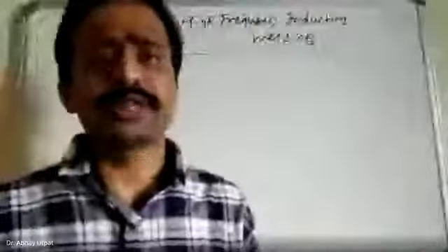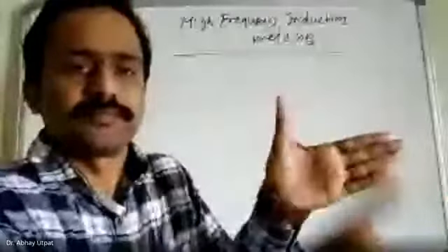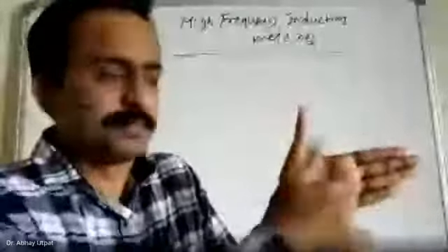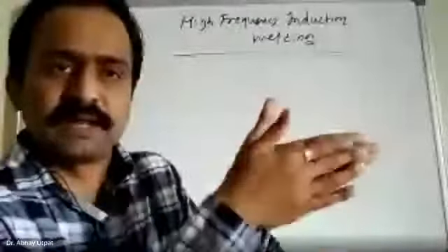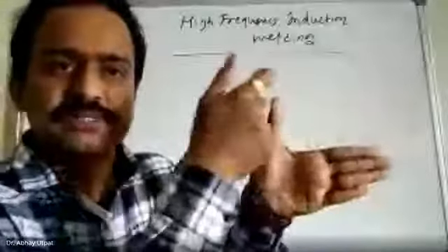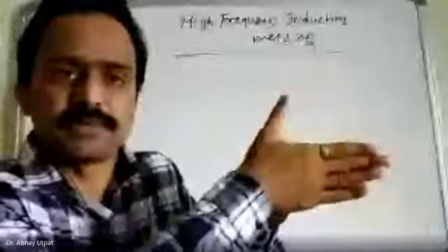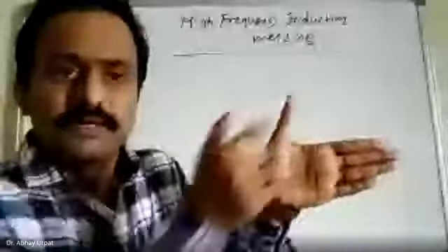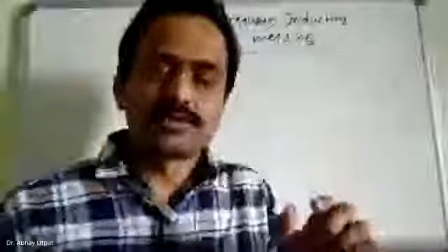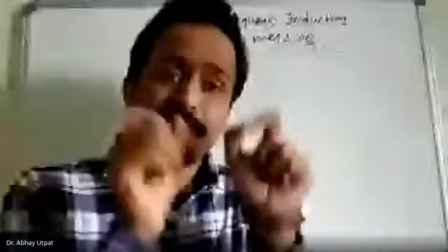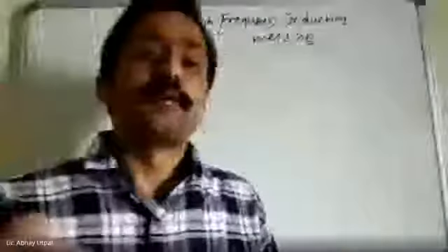When your joint is complicated, for example suppose this is an L-shaped joint, I want to join this, so I want an implant of this shape. See, same thing. Assume that there are no fingers, and see the outer line of this. So this is one complicated part, joined with another complicated part of the same shape. Now I am going to prepare one gasket of this shape, a washer-like material. That gasket is prepared from thermoplastic of the same material as the base material, mixed with metallic powder.